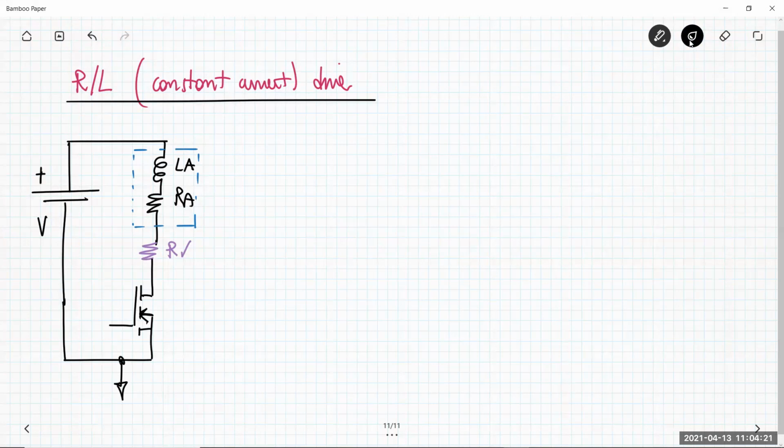So I add this resistance. Just consider the circuits, because at the turn-on both the previous circuits, with or without the freewheeling diode, are the same. Here you can also have the freewheeling diodes across the phase, and the circuit works as usual. But at the turn-on, the diode is off, and so there is no difference.